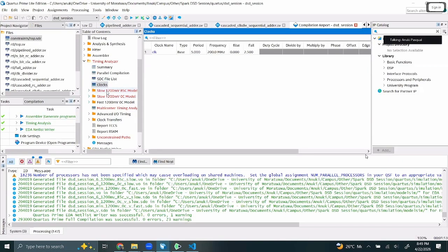Then these three things: it has done timing analysis under several different conditions. The delays that I have mentioned can change with temperature, and if the voltage changes, it might change too. Because of that, it's doing timing analysis under three different conditions.